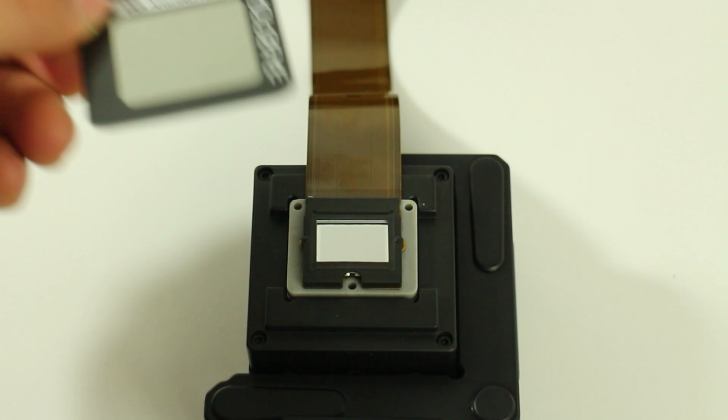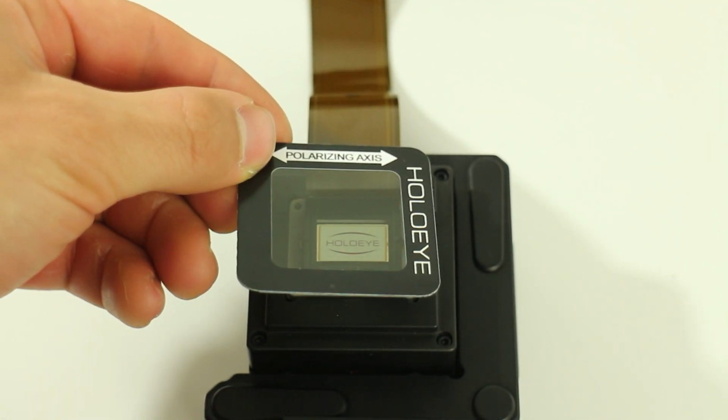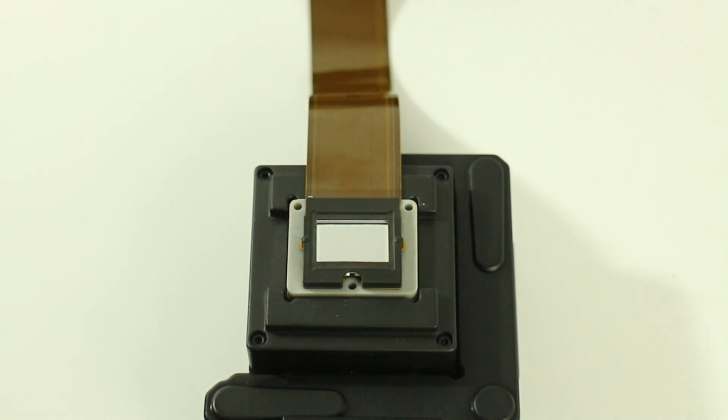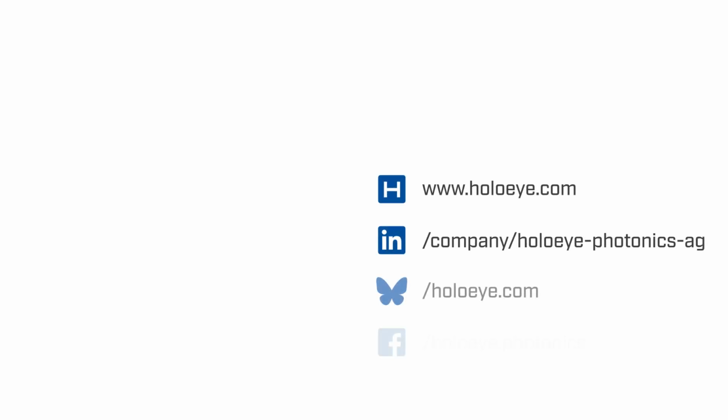Now place a linear polarizer on the display and turn it until you can see the addressed image. These quick tests work for all GAEA display versions, no matter which wavelength range they are optimized for. To use the SLM for phase modulation, additional settings may be required, as explained in the next video. GAEA 2.1 Spatial Light Modulator Configuration.